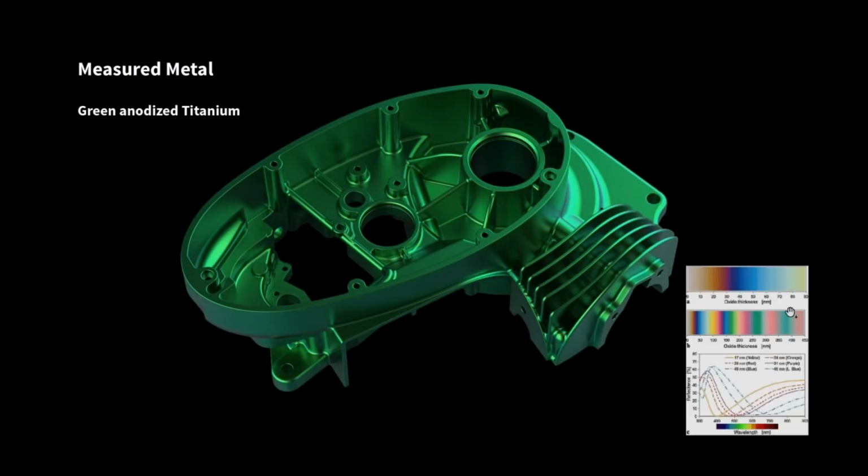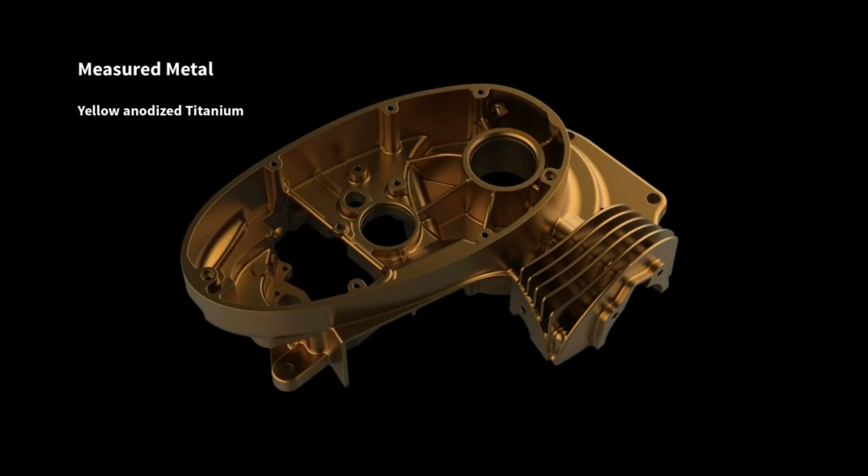And if you look on the internet for titanium oxide thickness, you will probably find some table or graphic like this one. And if you enter these oxide thicknesses inside KeyShot, it will exactly match the colors you will find in these diagrams. So it's a very accurate representation of a real world anodized finish. So here's a yellow anodized titanium just by changing the thickness basically.